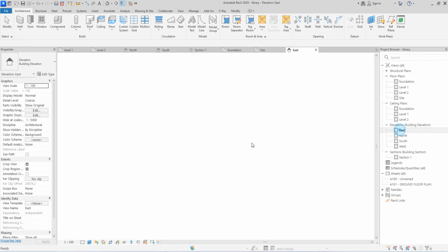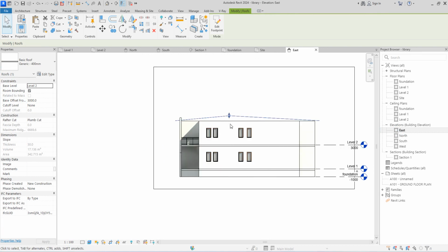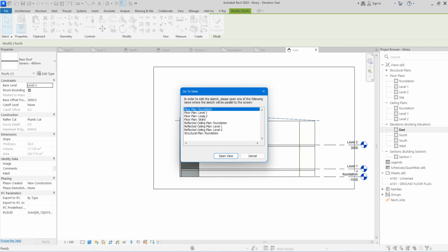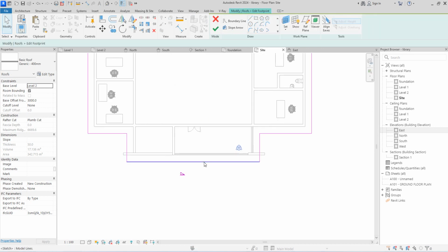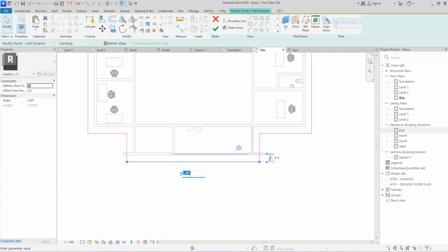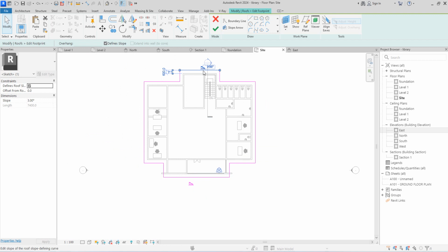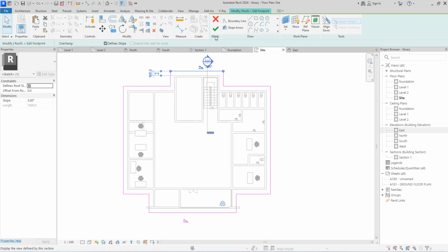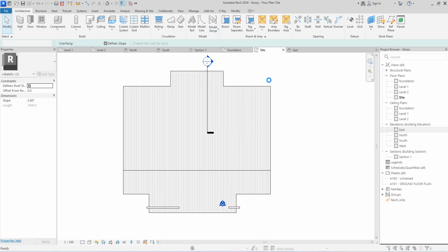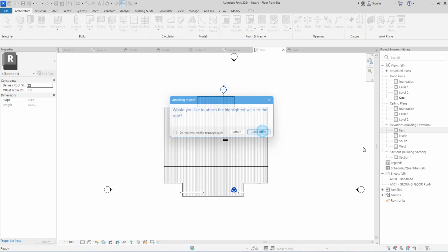So you go to the east side and see this is the way this forms, but we are going to readjust it because it's too down, which is what I mean that the slope is not enough. So 5, we are going to increase it to 7, while this one is coming back to, let's leave this one on 3 the way it was.